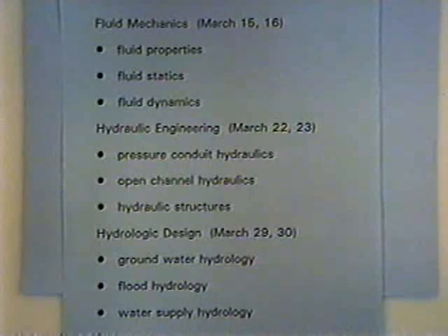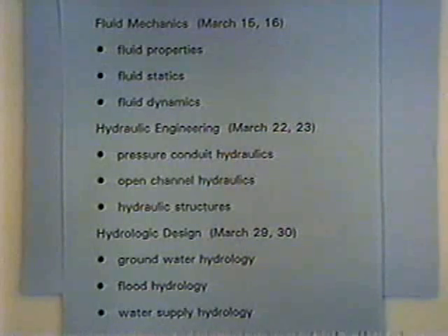And then week after next we'll move into hydrologic design, engineering hydrology, and look at groundwater hydrology and flow through porous media using Darcy's law, and then briefly looking at flood hydrology, which will include probability and statistics, flood frequency analysis, flood routing, dealing with flood hydrographs and flowing down a stream and through a reservoir and so forth. And then rainfall runoff modeling, the rational method, the unit hydrograph approach that's used in drainage design, answering the question, how much water should I design the culvert for, or the storm inlet for?